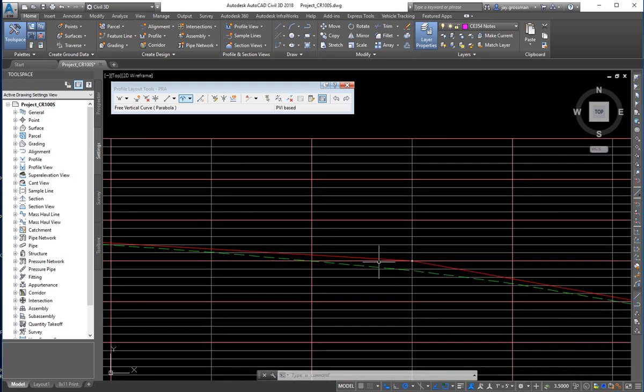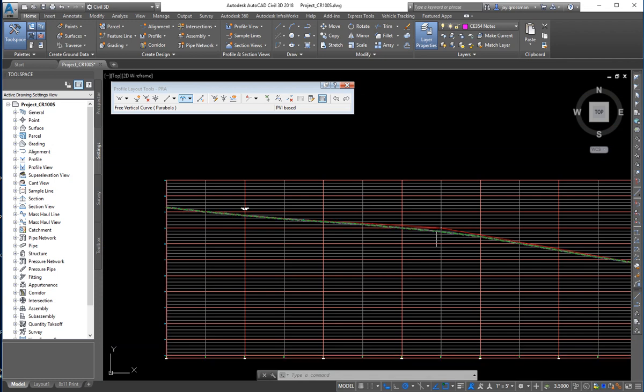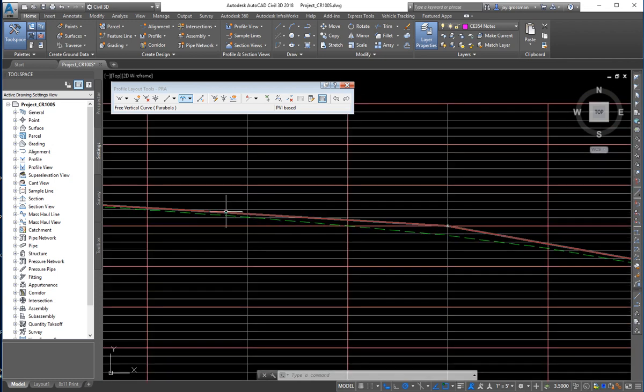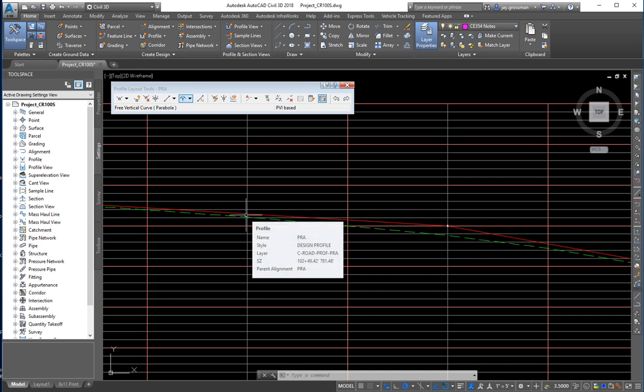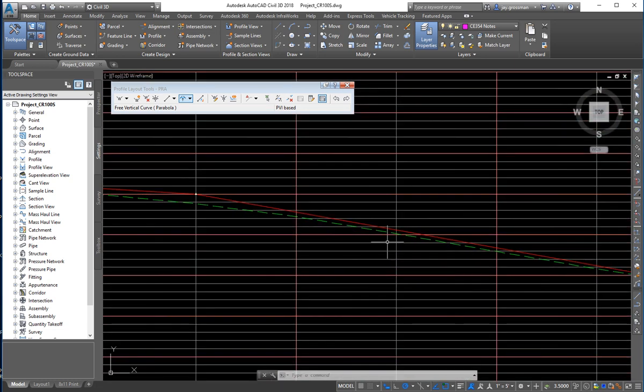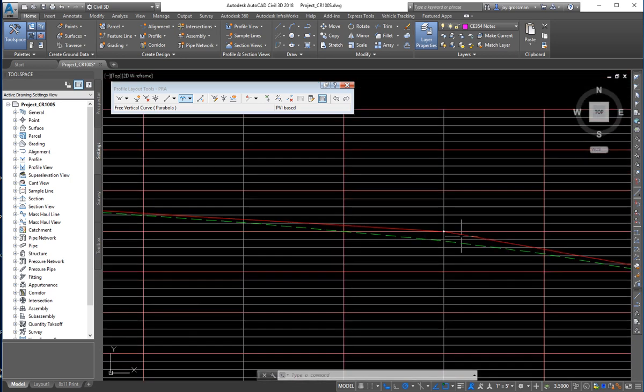Right. Now this one can be a really big curve. So we're going to make a big enough curve on this crest that we start way back over here. So that's what, 200 feet down, and it's going to go to this far side. So we're going to be in the 300 to 400 foot range. And even though the PVI is up here, if we put a long enough curve in, the actual height of the profile alignment is going to be back down in here.